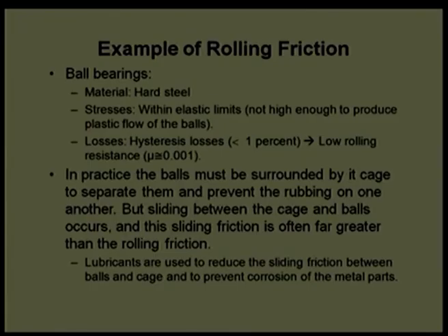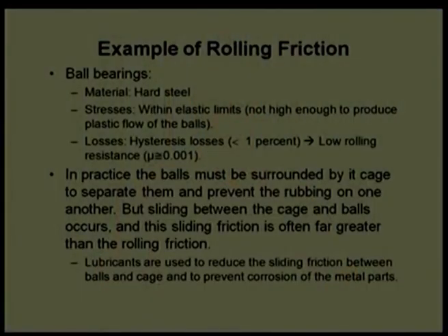We will be discussing those detailed expressions when we deliver the lecture on rolling element behavior, rolling element bearing design and selection of rolling element bearings. However, I am just providing two simple examples on this slide. With a ball bearing, we assume they are made intentionally of hard steel, so the deformation is negligible, it can really roll, and the roll to sliding ratio is very high.